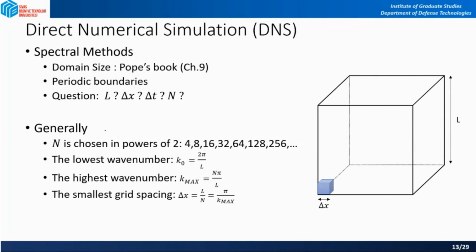So you need to do LES, you need to do DNS. We will cover both mathematics and physics of LES. But before that, let's finish this DNS. It's a very short discussion. So we do a lot of homogeneous isotropic turbulence DNS to understand the physics and mathematics of turbulence and to help us develop new models that can be used both in LES and eddy viscosity modeling, for example.